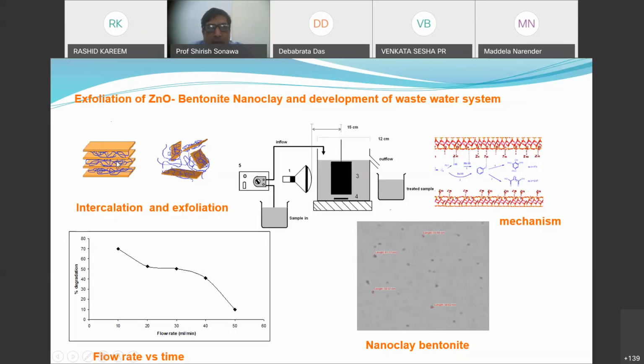Each clay particle will have almost 800 to 1000 platelets put together in a single clay. This is a unique structure in which we can separate out each platelet, and that is going to help you improve properties such as mechanical property, tensile strength, flex modulus, and impact strength.